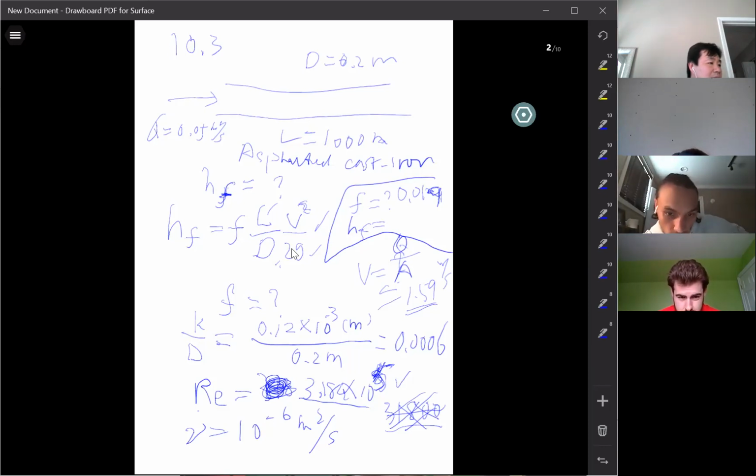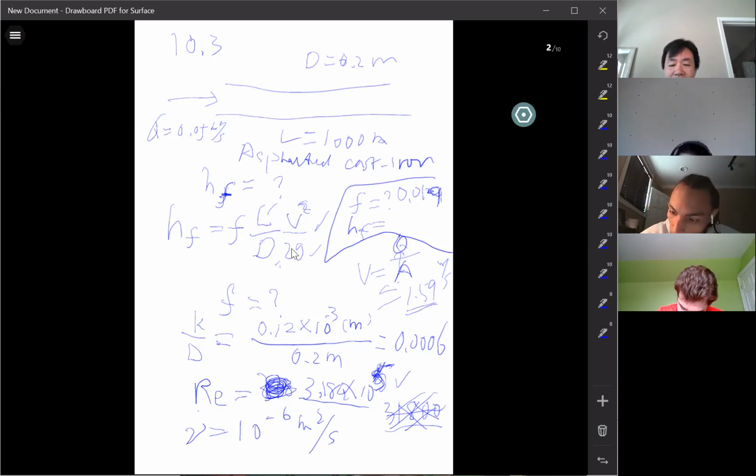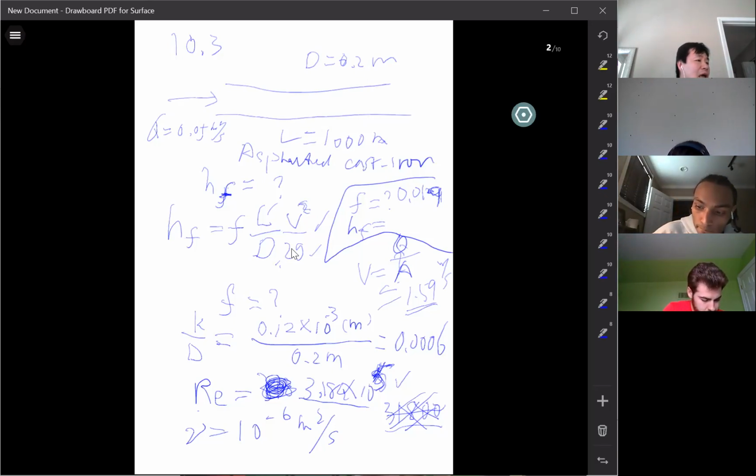Dr. Zhang, I got a little bit lost whenever you were doing the Reynolds number. What value did you say was correct? 318,000. So 3.18 times 10 to the 5. The correct answer is in the textbook, but eventually the value is not important. We need to remember the process. In the exam, I'm pretty sure I can say this, it will have the problem. You need to use Bernoulli and the Moody diagram. So you really need to know the process. Remember the process.